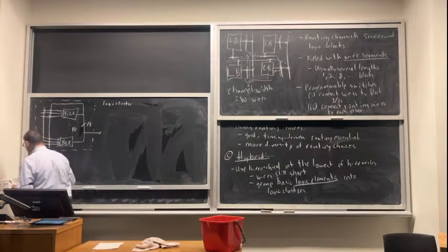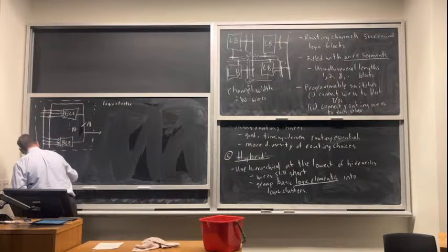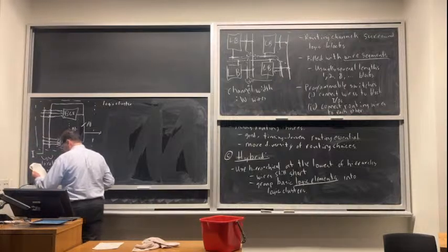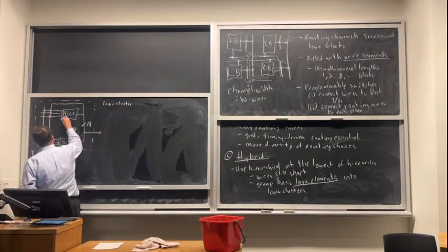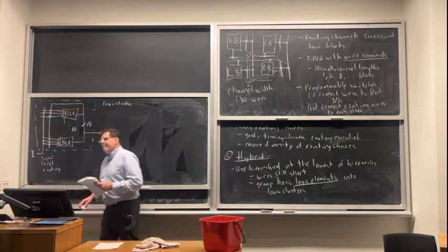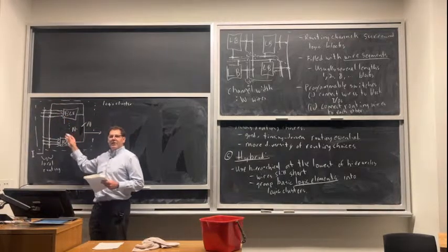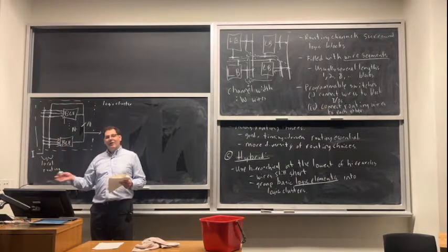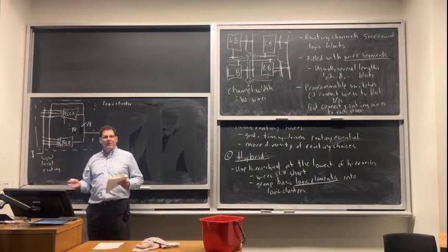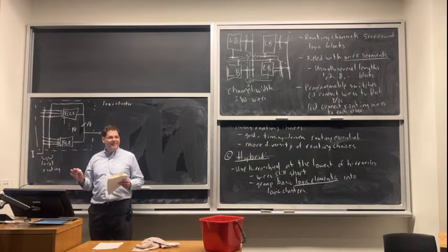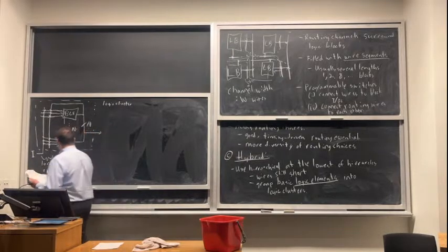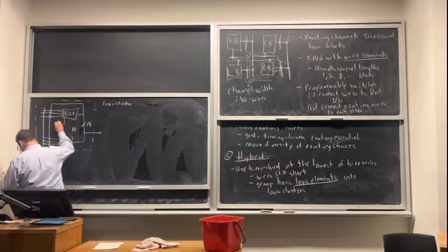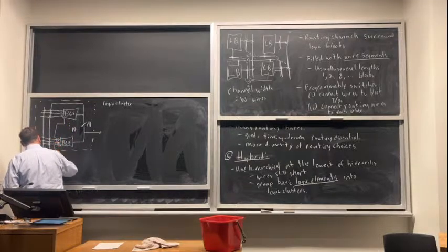So this is some local routing. It's like your level 1 routing. And normally we don't need things like clock signals to go to just one register. If you have a whole bunch of clocks that only go one place, it's somewhat of a strange design. Okay, you should look at how you're writing your RTL. So usually your clock goes to a whole bunch of different registers. So we can also do things like have special clock inputs.